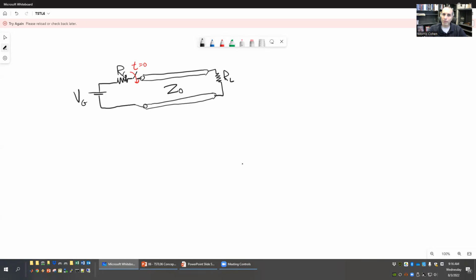And if we wait long enough, as t goes toward infinity, we're going to simply remove the transmission line and replace it with 2 simple wires. And we've got VG connected to RG and RL. Right, after a while, the whole circuit will approach what we would call a lumped system anyways, where everything is just mushed into one point. Again, after some amount of time has passed, enough time for those back and forth ping pongs to settle out.